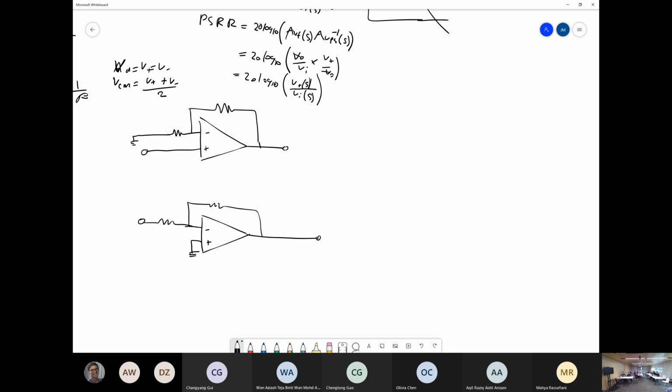You said one of them has better common mode performance. Why is that? What's the value? So if this is V in. Yeah, there's a resistor in the way, right? Sort of, you're close. What's the value of this voltage here? Now, if the op-amp's operating perfectly, it's not slew rate limited, it's not bandwidth limited, what's the voltage here at the negative pin, the inverting pin?